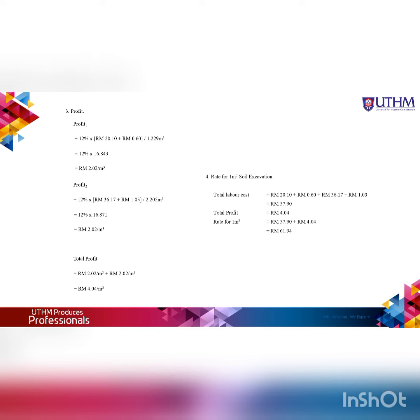After that we will find the profit, and then sum up the profit to get the total profit. Then we will find the rate for 1 meter cube soil excavation by knowing the total labor cost and total profit, and summing up the total labor cost and total profit to get the rate for 1 meter cube for soil excavation.